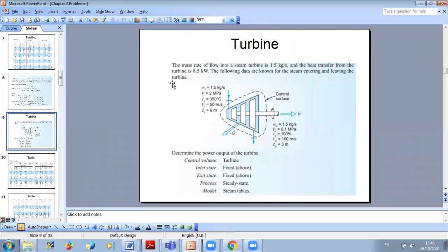Now, for the outlet, it depends on the cycle. You can have a point just at the saturated vapor or a little bit inside the curve. So in general, you should look at the saturated tables when you want to look at the outlet conditions. Now here, for example, I told you that at the exit, you have X. X is the quality. X exit is 100%. This means that I am just at the saturated vapor point. So I will go to the saturated tables to get H vapor at this point.